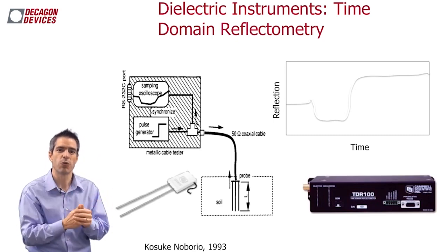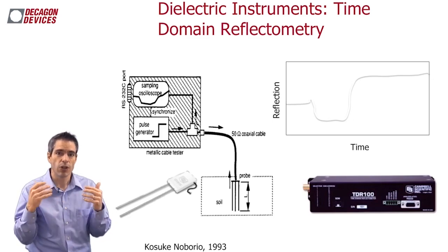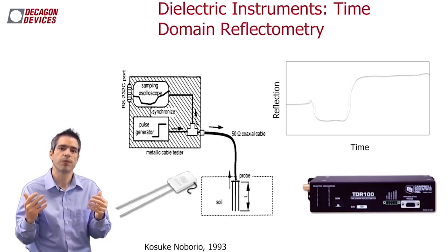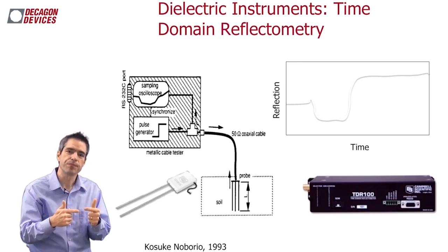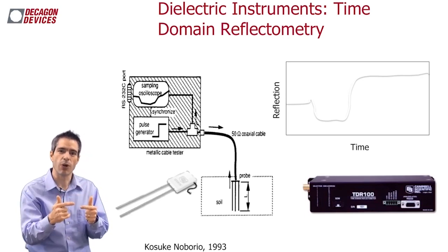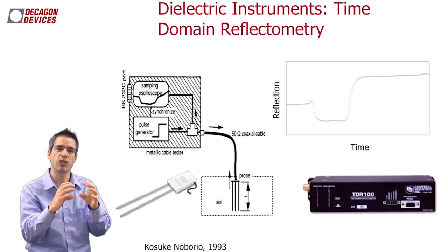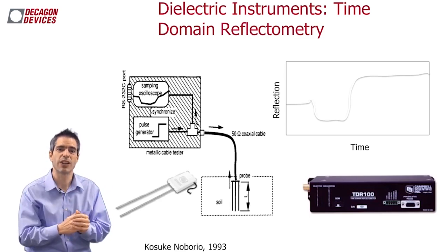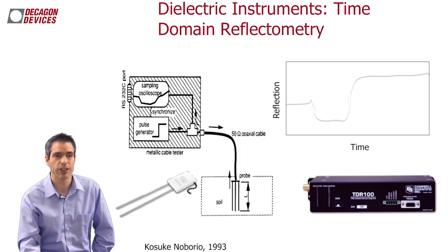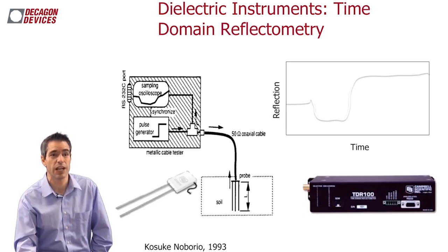exactly where the break was. And Clark Topp and friends thought, well, I wonder if this would work for measuring soil moisture, because they knew that the speed this pulse traveled was slowed as the charge storing ability of the material around this cable increased. And so he decided to test this out, and this is the cool thing that he found. This pulse generator produces a pulse of electromagnetic radiation, which you can see right here. It travels down this cable, reflects off the end and comes back.